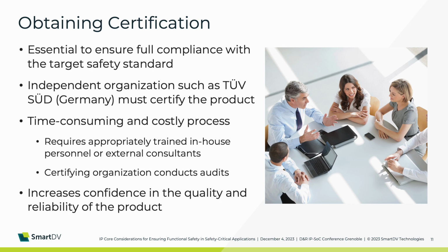On the negative side, the entire process up to obtaining a certification is time-consuming and requires appropriately trained personnel. It is also necessary to carry out audits with the certifying organization during the entire period of certification, during which the completeness of the measures for achieving functional safety are checked and proven. On the positive side, certification can increase customer confidence that a product has the quality and reliability that they are looking for. In most cases, it makes no sense to certify individual subcomponents such as IP cores, as these are used in the context of a more complex circuit anyway.